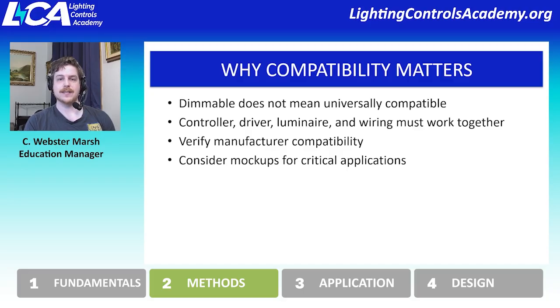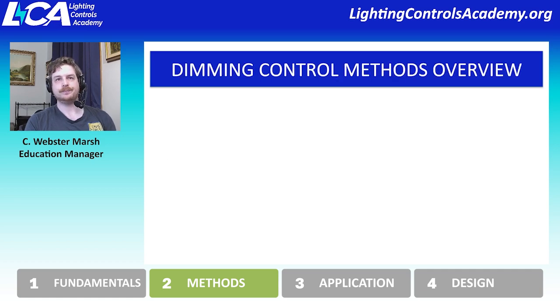Oftentimes I will mock things up with a new dimmer that I'm unfamiliar with, and sometimes it does show, oh, this behavior is going to be really unsavory, and I do not recommend you use this dimmer. Whereas other times I might be surprised to find out, oh wow, that dimming is really good. I think that this is going to work really well for the project we're working on. So making sure that either you've confirmed with the manufacturer or done your own mock-up really makes sure that that compatibility is there, because the compatibility really does become a critical function of dimming, and making sure that that is going to be a high quality dimming performance.